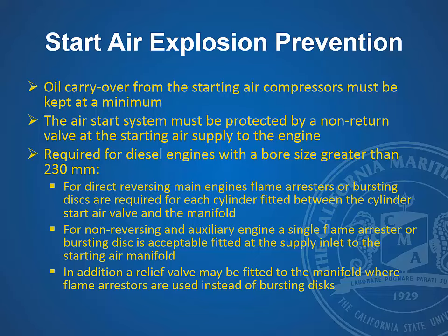To prevent a start air explosion, you want to minimize the oil carryover from the start air compressors. The air start system must be protected by a non-return valve at the starting air supply to the main engine. It is a requirement for diesel engines with a bore size greater than 230 millimeter.